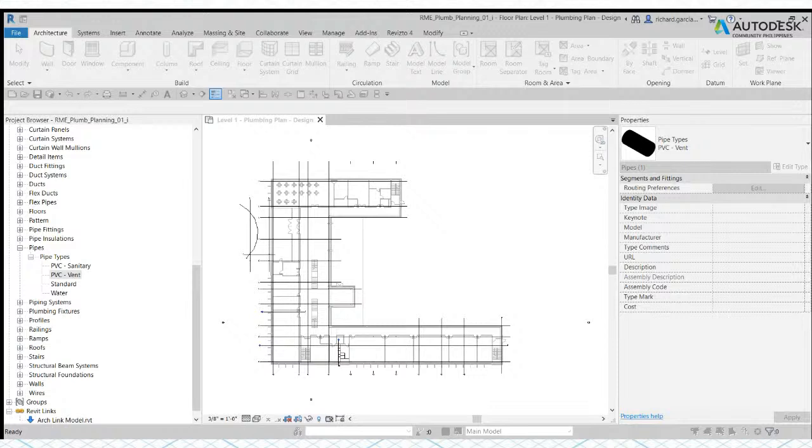Okay, now if you want to create a new type, or you want to add size for your pipe, you can actually go to the segments and sizes, just click that one, and there you go. So you can look for the material that you are using. So I'm using plastic schedule 40. So what I can do is I can click the segment here on the segments and sizes. Just click that one, click the drop down arrow, and then look for the material that you are using. Click that one, and there's now your plastic schedule 40.